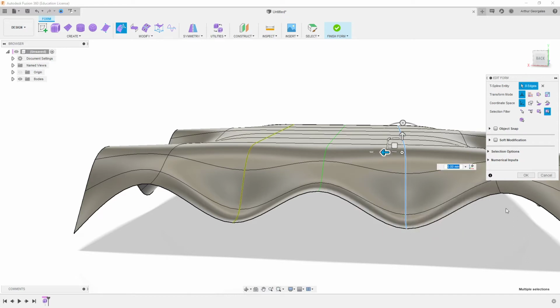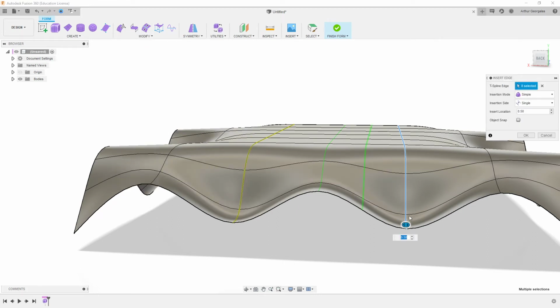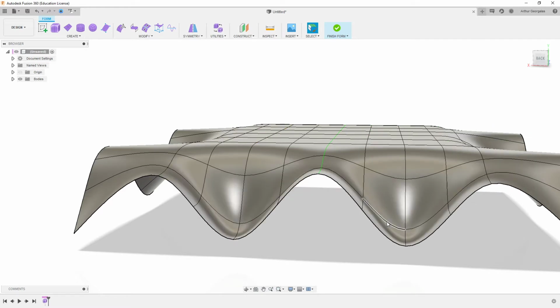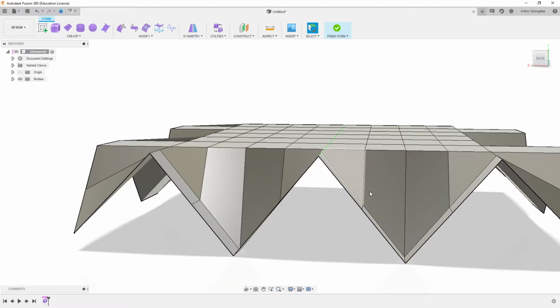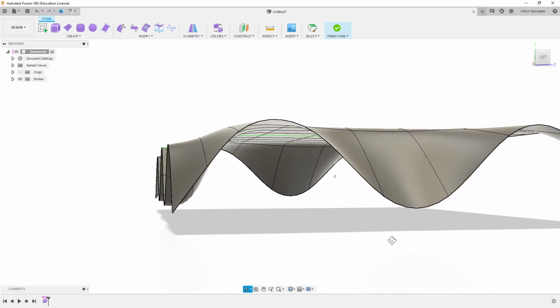And then if we want it to be sharper down low, we can actually insert an edge right over here and right over here, and that's going to control the way this blends in. Because we got symmetry turned on, we only have to do it on one. So if we go to insert edge, we can do that. But we also want to look at maybe doing it on both sides of this, so we can control both of these at once. So if I just go 0.5 right in the middle, that might take a second. You can see there, it's blending it a lot further. So instead of going all the way from here to here, it's going from here to halfway, and then from halfway to the bottom. And that already brings it almost right down to where we want it.